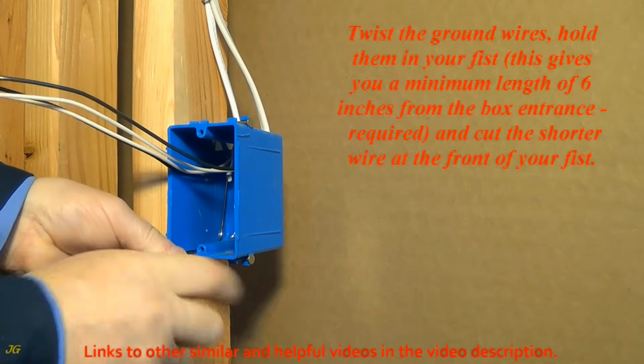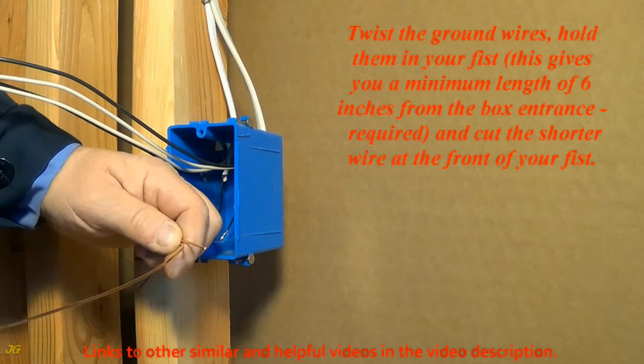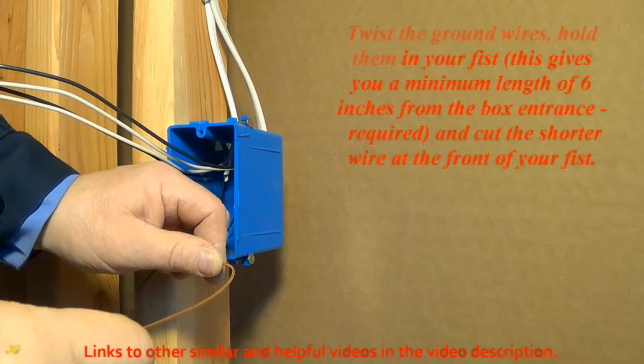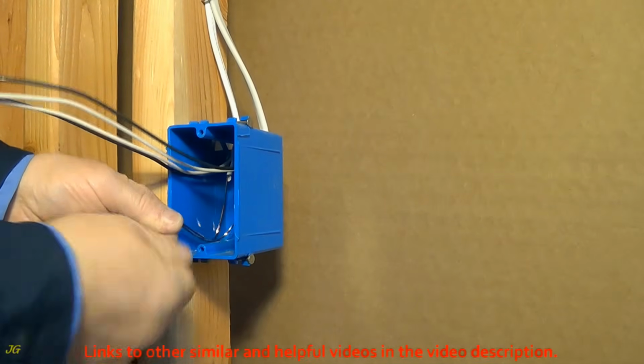box. Twist the ground wires. Hold them in your fist. This gives you a minimum length of 6 inches from the box entrance, required, and cut the shorter wire at the front of your fist. Pull the long wire through the green wire nut hole and twist it clockwise.